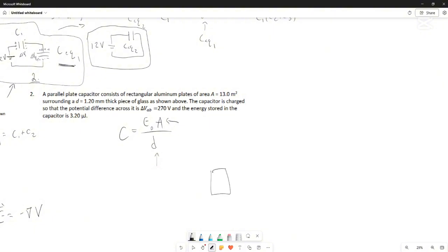And we're assuming that the plates are parallel plates and they're squares. So actually, we're not assuming they're squares, but we're assuming they have some area and it's some sort of rectangular shape and they're in parallel, and that's why we draw capacitor elements like this, even though they're not always parallel plate capacitors. There are different types of capacitors, but this is a simple one for which I derived a formula in class using Gauss's law.